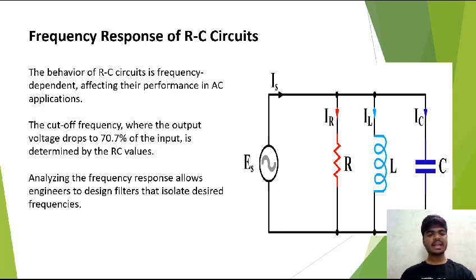This is the frequency at which the output voltage will be equal to 70.7% of the input, and it is determined by the RC values. By analyzing the frequency responses, engineers design filters. Using filters, we can get the desired frequencies from the given input voltages.